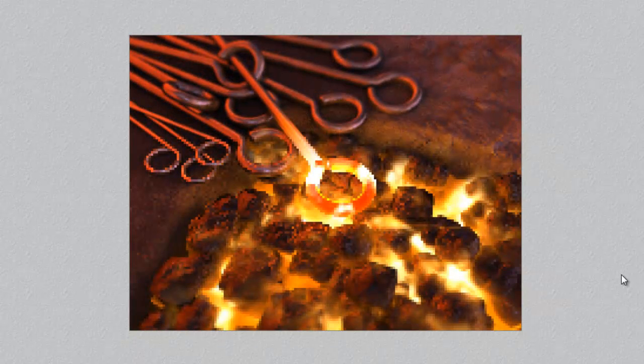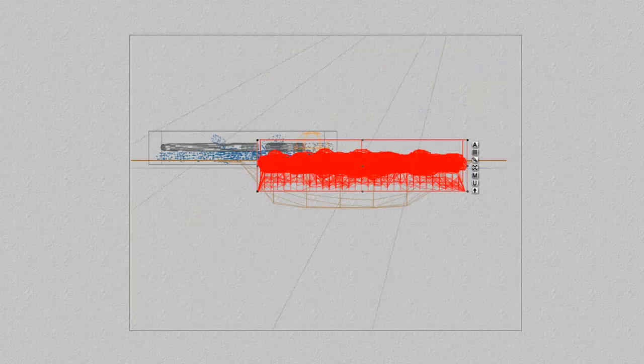Okay, it's reporting about 15 minutes. That's not too bad, as long as it's not too grainy in the background there. Looks like an appropriate level of blurring. Okay, as you can see, I've given that a bit of a render. The background's a little bit too grainy, so I'm going to have to take the rays per pixel up a little bit, and I'd like these coals to glow a bit more.